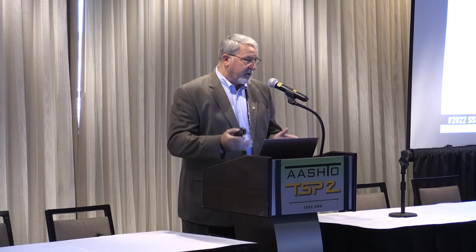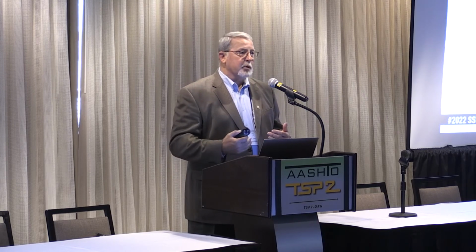Well, there's several questions in there. First of all, I'm not a fan of an agency dictating what the job mix formula should be. They can have a range of residual asphalt contents. I think ISSA recommends somewhere between 6 and 9. I do know some agencies that have bumped that up to 7 to 10. But ultimately, I like to rely upon the performance testing and the mix design to dictate what that content should be. Simply put, they're putting it through rigorous performance testing in the laboratory, and who am I to grab a number out of the air to determine what that content should be?